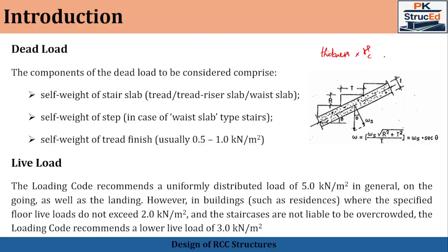This gives the value perpendicular to the axis of the slab. But in this case, the axis of the slab is an inclined one. So the self weight calculated by this relation acts perpendicular to the inclined axis. But when designing the reinforcement and calculating moments, the load should be considered vertically.